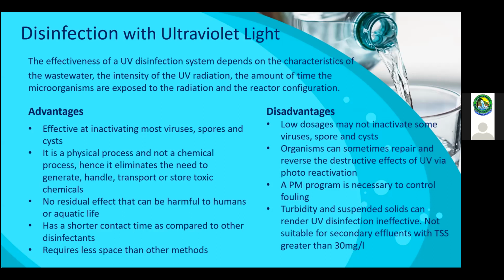It has a shorter contact time as compared to other disinfectants. Typically, chlorination would be around 30 minutes, in some cases a little bit more. UV radiation is in a matter of a couple of seconds, 30 seconds, 45 seconds. It requires less space than other methods.